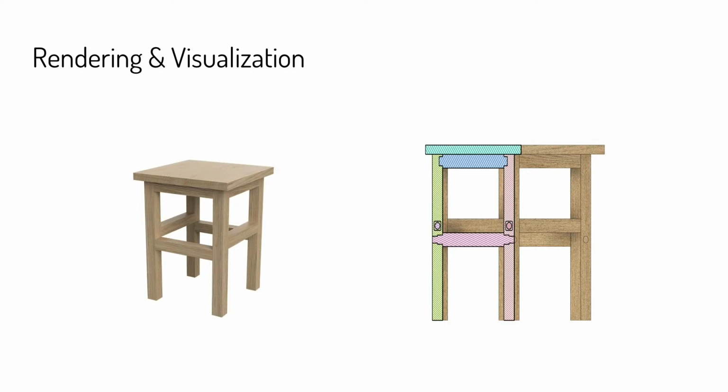The basic idea here is that on the left side of the screen is a wood-textured rendering that Fusion produced. It's really easy to do. We'll look at how, but it's quite straightforward to make really nice-looking wood project renderings. On the right-hand side is a section view that you can use to analyze how your project is going to go together and get an idea of, for lack of a better word, the inner workings of your joinery, so that you can make sure it's all right.